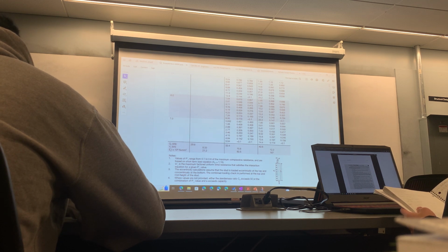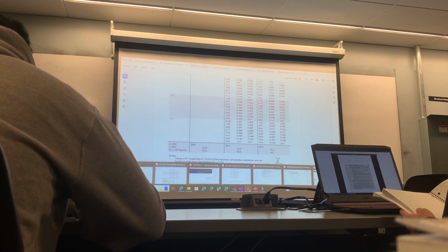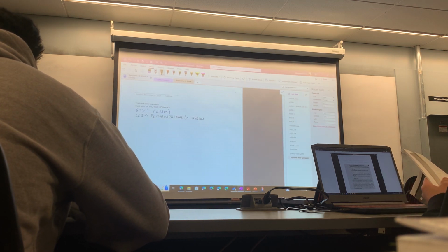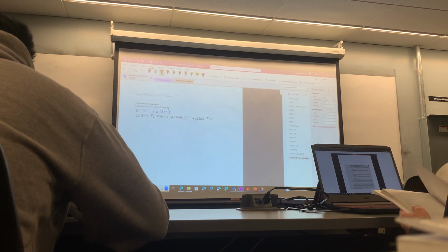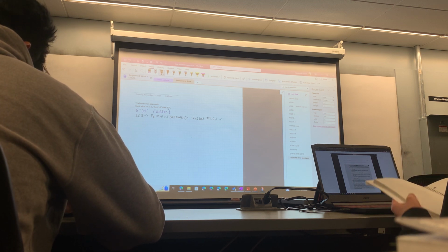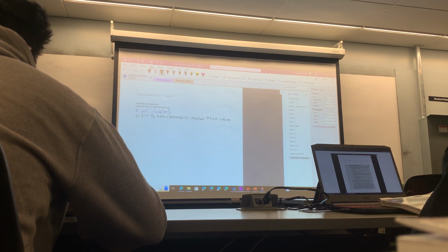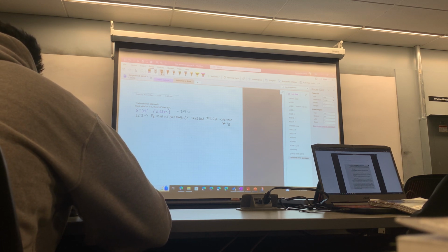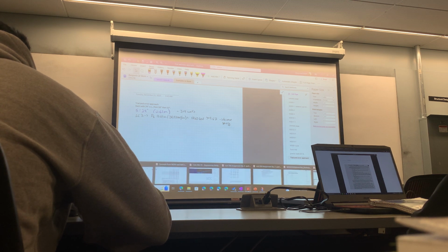I'm just going to start this off and we'll continue this tomorrow, but to put it all together, this is greater than 9.67, therefore decrease spacing. We're doing this for 2x4 walls. So right off the bat, if you're at 24 inches on center, 17.63 is greater than the biggest number.